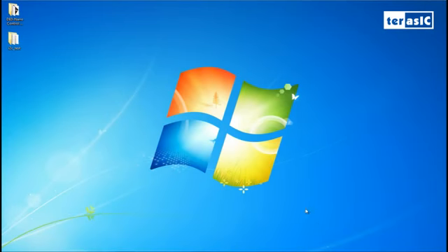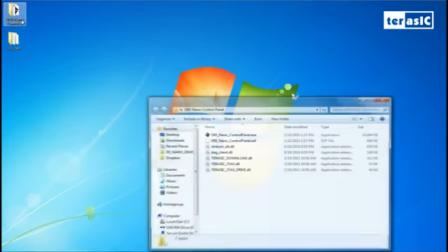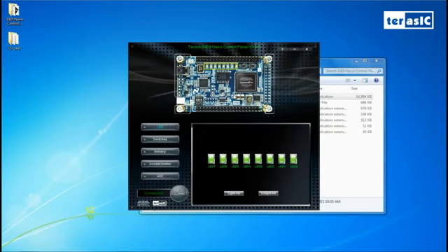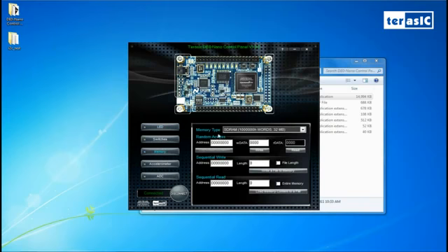So before we start coding our DE0 Nano I2C communication, let's open up our control panel. And I've already connected our FPGA dev kit onto our PC. So it's automatically detected and connected. And if we go down to memory, we can specify our memory type to our EEPROM to control our EEPROM. Over here we have random access. So at address 0, we can write whatever data we want and read from it as well.